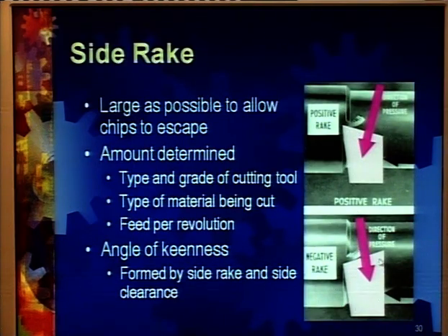But in case we are using a carbide tip tool, since these tools are very fragile, we will need to give it a negative rake angle so as to prevent its breaking off. Similarly, it will also depend upon the type of material which is being cut. Some materials try to stick onto the negative rake angle, because they try to get attached to the material of the cutting tool, and there are certain other parameters also which determine